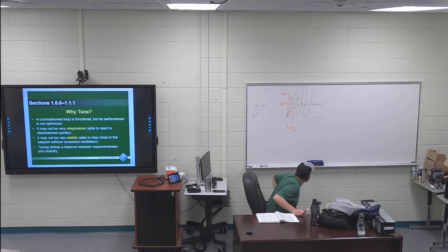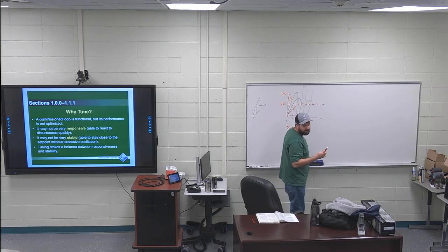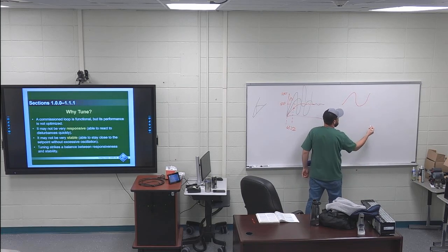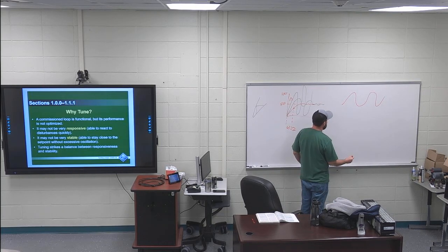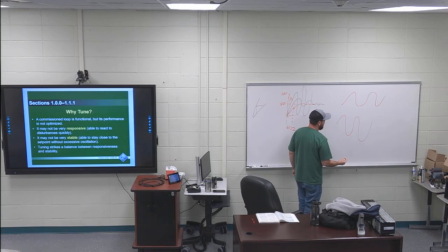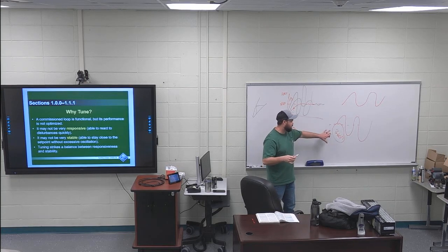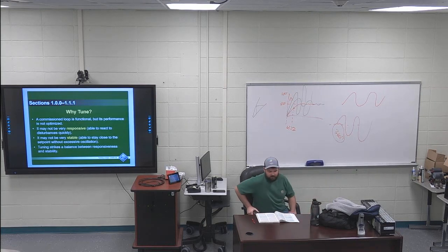So just looking at these, once you get uncontrolled, what it means by 360 degrees is, if you constantly have sinusoidal waves like this, I didn't do that right. There we go. If you constantly had that, and I'm splitting it right here, if I took this half and put it right there, it's just a big circle, 360 degrees. So if you have 360 degrees of phase shift, it's bad as far as trying to control it.